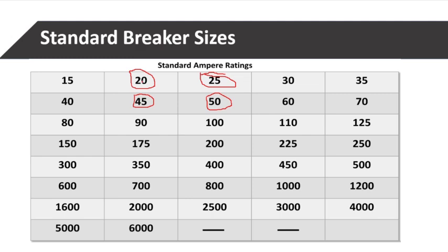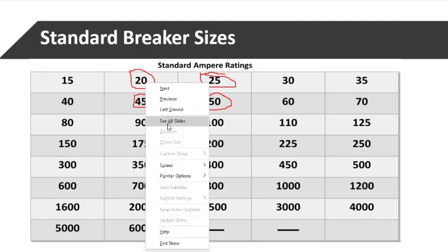The cable will catch fire because of the excess current, and this breaker will not do anything, because it can allow 45 amps to pass through since it's a 50 amps breaker. Now this cable will catch fire and your inverter or your house will burn, which is the most expensive mistake you should always avoid. Do not oversize your breaker.